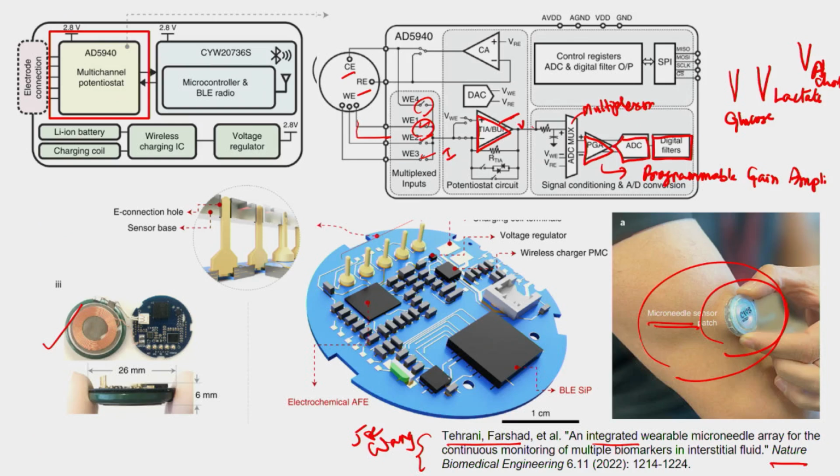And let's say we are sitting near electronic devices. There is some feed through or electromagnetic induction. At 50 hertz we have an AC signal, which is powering up our devices. So that 50 hertz might also come in. So that can be removed using filters.